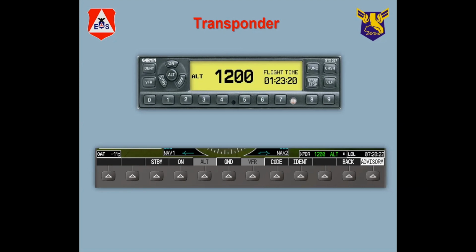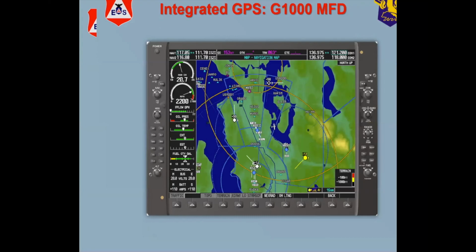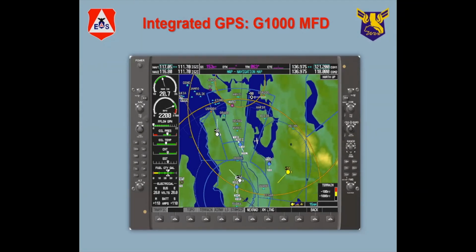And when they ask you to squawk your transponder, that means you push a button, and when the radar hits your airplane, it's going to pick up whatever number was in there and identify that on the radar screen. If you look down here, on the right-hand side, there's a yellow dot with a line on it and the number +12. That's the return and identifier of a particular aircraft, and it's when a radar inquiry was made.